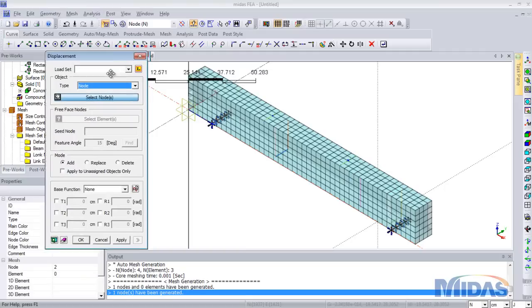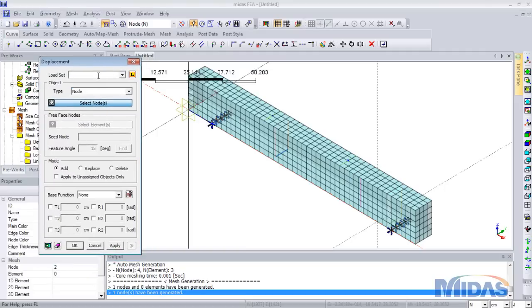So for certain cases in which we have to simulate crack propagation, or the crack propagation analysis, the displacement controlled loading scheme is much more convenient and reliable. The results we'll be getting are more detailed and realistic. However, if you are doing the load control, that would not simulate the cracks quite as well. The model may not converge, or it would end after the tensile stress has been exceeded. So that is the reason I'm simulating it with respect to the displacement.